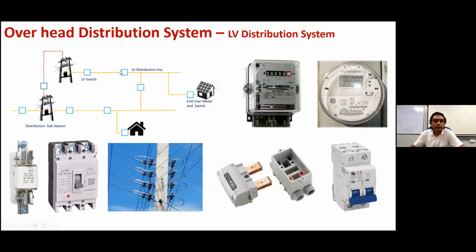Again, I want to discuss the switches. As I discussed for the MV distribution systems, there are not many switches in the LV distribution system. Very few switches are used in the LV distribution network. The practice is that the transformer output feeds a protection device called an HRC fuse or MCCB, shown in the figure. The function of both is equal.